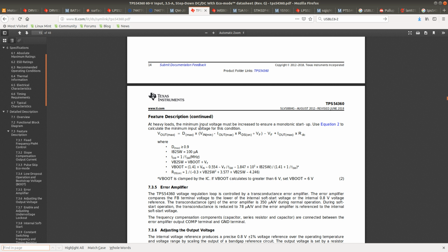And the output voltage can overshoot in case, for example, the load current suddenly increases. And what this means is that it's very important to ensure that the output circuitry is able to handle these overshoots. Because if you have, for example, a processor module, this is a problem that I had before when I designed a 3.3 volts supply using a buck converter similar to this one.